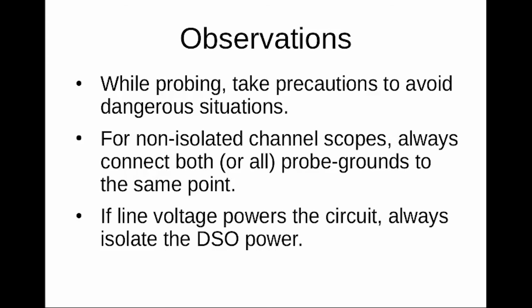most of the power electronic circuits are having floating voltages, like some points in the circuit may be swinging to either a high voltage or a ground level voltage, depending on the status of the switching device, on or off. Now in a non-isolated oscilloscope, both the grounds of the oscilloscope are the same point. Now let me explain that with the help of a drawing.